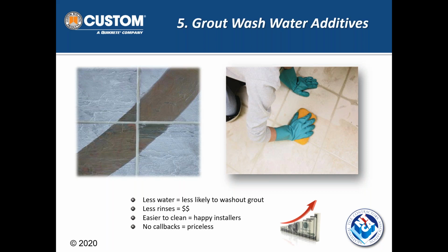What they do there is use less water, less likely to have the washed out grout or dishing and cupping of your grout joints, and fewer rinses. If I'm the guy grouting, and I've been there, I've used these myself on families' jobs or people's jobs that I've installed tile. For me, I don't want to be on my hands and knees longer than I have to. I don't want to have to do more rinses than I have to. I don't want to have too much of a problem with the color of the grout, especially if they're mid or darker tone colors. It makes it easier to clean. Everybody's happy, no callbacks. This is what we're all looking for, right?